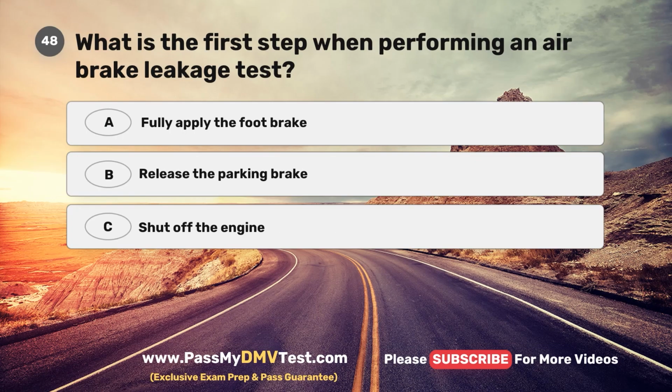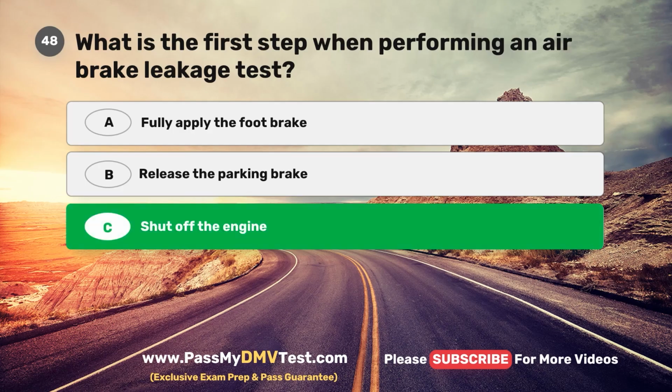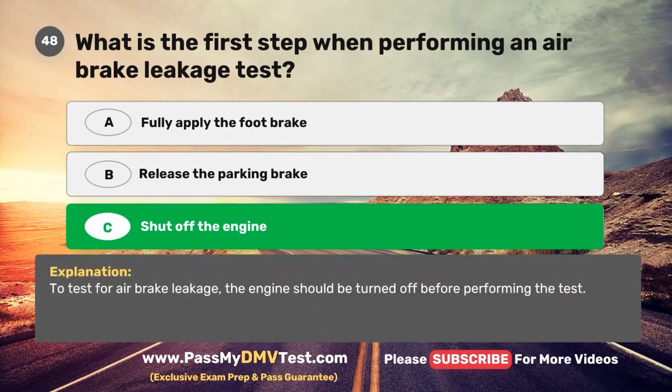Question 48. What is the first step when performing an air brake leakage test? A. Fully apply the foot brake. B. Release the parking brake. C. Shut off the engine. The correct answer is C. Shut off the engine. To test for air brake leakage, the engine should be turned off before performing the test.